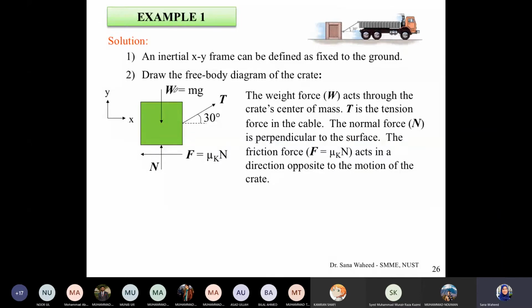Pretty straightforward. Note that I've just set up my coordinate system, xy like so. Anywhere, origin doesn't really matter right now because I'm not interested in my position at this moment. That's why. Perfect. And then from this, I know the normal force is always going to balance the vertical forces acting on it. That is, it's not suddenly going to start jumping in the vertical direction. In the vertical direction, it is going to be in equilibrium.